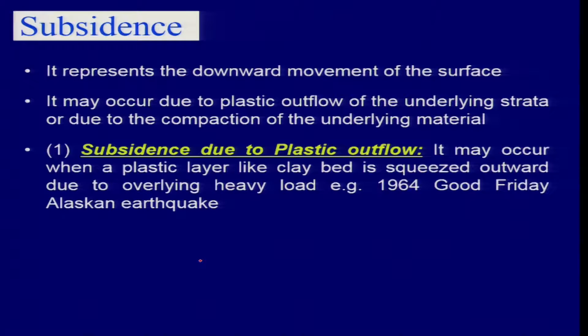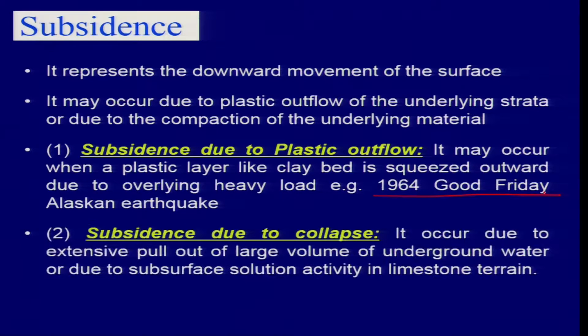Subsidence due to plastic outflow, this is the same example of the Good Friday earthquake, or you are having subsidence due to collapse. It occurs due to extensive pull out of large volume of underground water. So, you are extracting groundwater at a very high rate, and that can also result in subsidence, or due to the subsurface solution activity in the limestone terrains. So, one is large removal of groundwater, another is the solution activity in the limestone terrain.